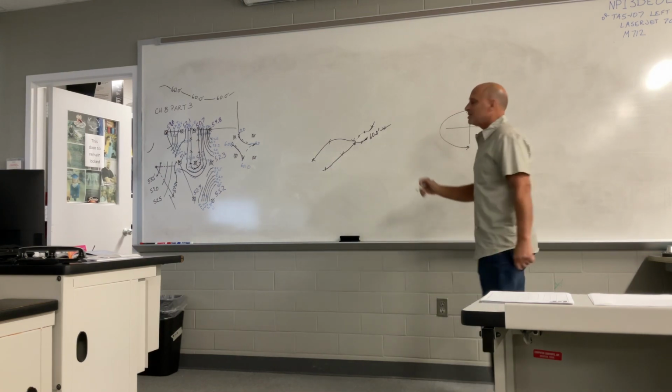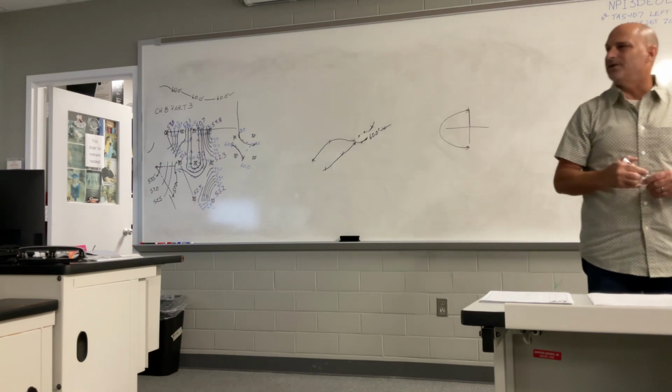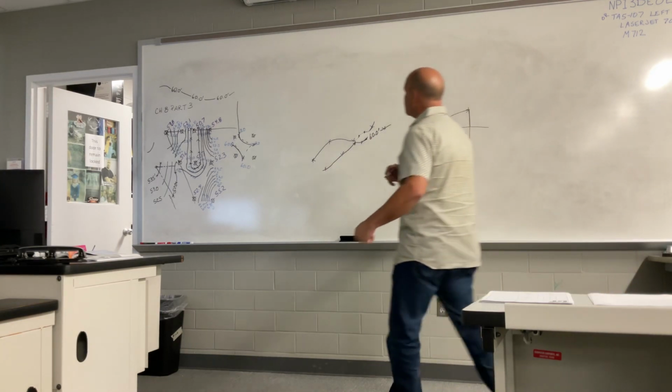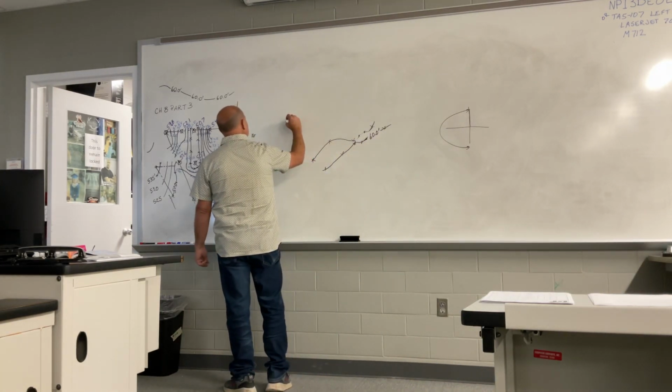So when you're putting that text on there and you're like, well, I don't know about that angle, that might be upside down. Single click on it and go to your properties. If that property for that text says that the angle is between 90.1 degrees all the way around to 270, rotate it 180 degrees. So everybody understand that? All right, so on this project, your interval is 0.5 feet.